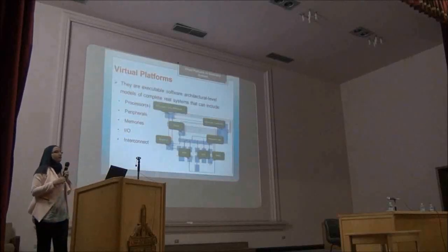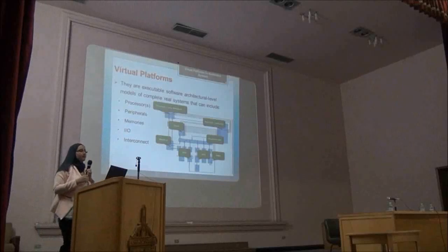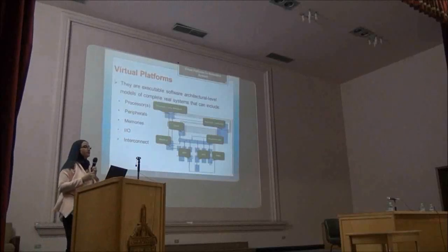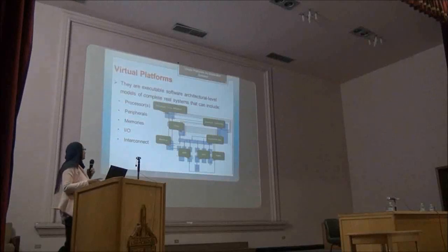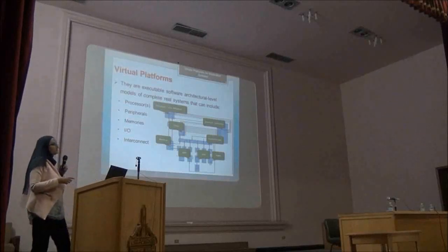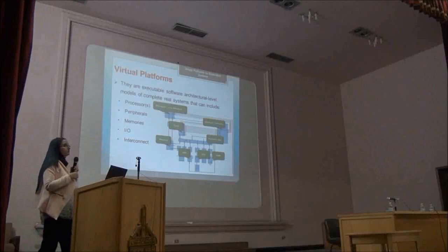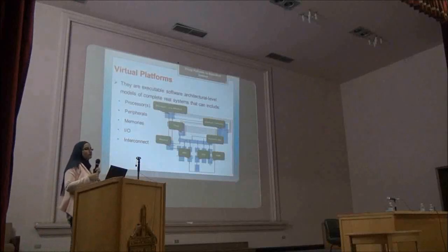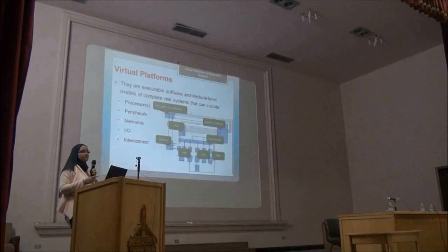Virtual platform actually is an executable software for the complete real system, including the processor core or multiple processor cores, and the interrupt control unit, timer, analog to digital converter, CAN controller, display controller, whatever you have in the system on chip.